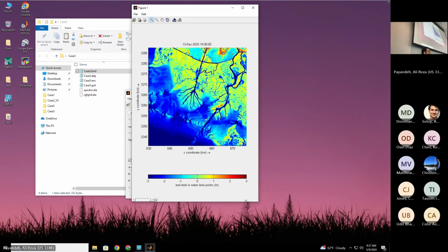Noticing the differences between the bathymetry from the current condition, January 1st, 2024, and then the next 10 years may be a little hard because this model is only having sand, and with sand, we will not have that much change in bathymetry. That's why we are going to have case 4 with sand and mud together. Most of the sediment here is mud. That's why we need to add mud, and then we will see more changes in bathymetry.